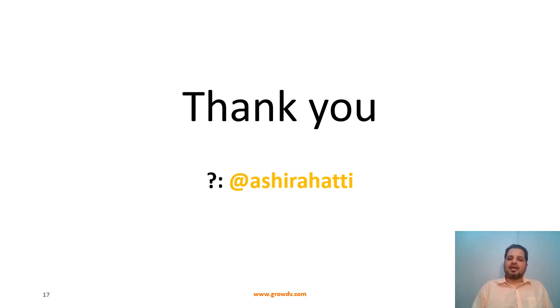And we have looked at how to structure the functional coverage model with the help of auxiliary logic, along with your cover group and the assertion based coverage, and how your auxiliary logic helps you to massage the information coming in from the DUT as well as from the test bench to provide two key sets of information: when to sample, what to sample. It provides that information, which is consumed by your cover group or assertion based coverage models, and they provide you those metrics.